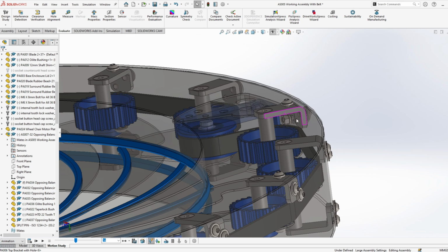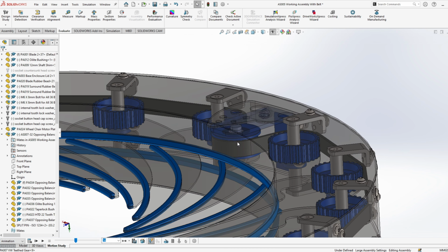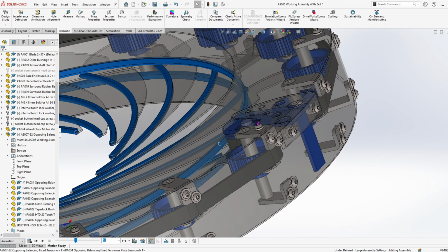So that's really it. The plate at the top here, the handcrafted creative face part with all the holes, is really just placed here to hide this heavy duty stainless flat bar used to support the gear. But it also assists with the adjoining plate that bolts to the enclosure with the two M6 bolts seen at the rear of the tensioner here, as I've mentioned.